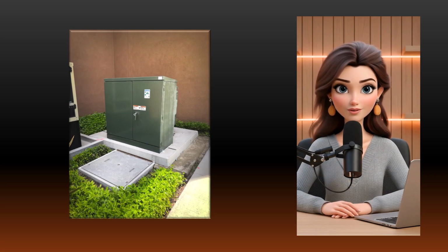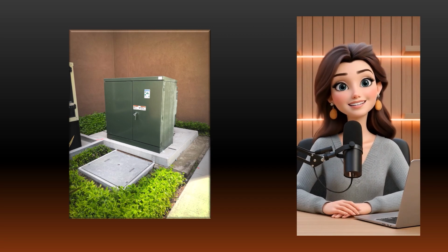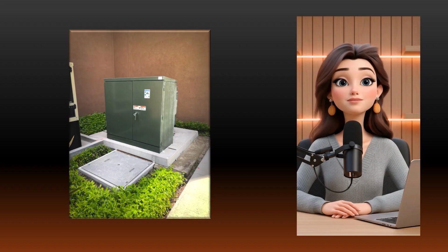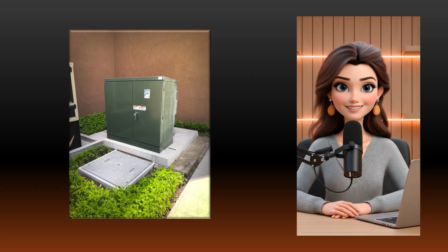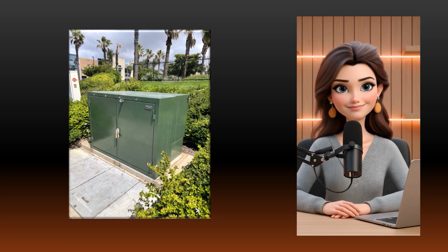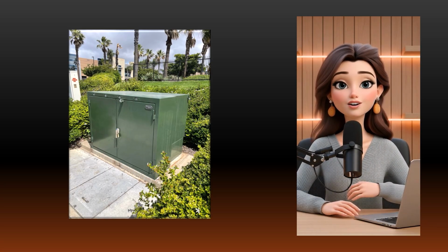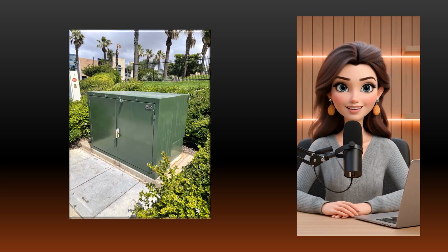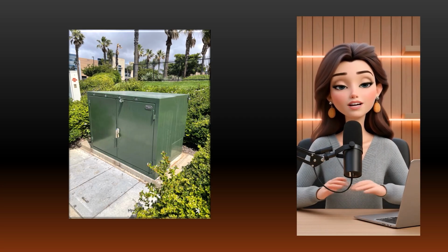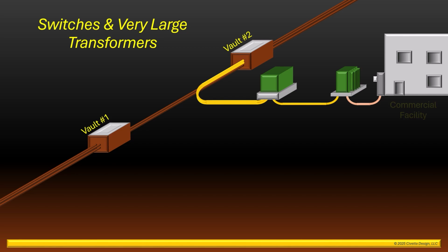This type of transformer is available in a variety of sizes and serving voltages, and connects to the main distribution system in a manner similar to the smaller one. However, the largest of these transformers require the additional installation of a high voltage switch. The addition of a switch allows the utility to energize or de-energize the large transformer for maintenance or emergency purposes whenever necessary. Let's take a closer look at a commercial development requiring a switch.